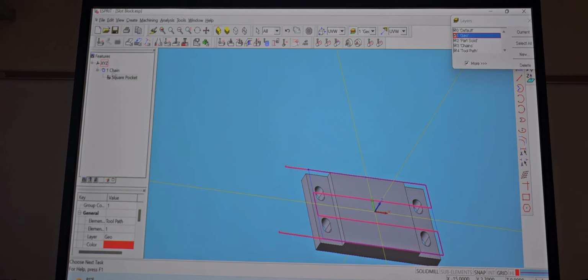So, over here though, I missed a step real quick. You guys see how it's highlighted, but it says layer geo, right? If I highlight this, it says layer geo, because I had geo highlighted the whole time, correct? Quick fix on that chain, I'll just click over here, chains, and I'll just click this one, quick fix, toolpath, boom.